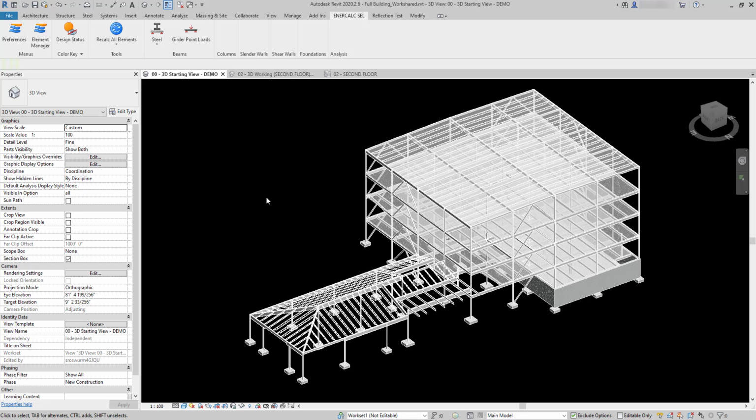In this video, we're going to be looking specifically at hosted Revit load objects and launching a beam that has those already existing in the Revit model. Now, as I mentioned in previous videos, it's perfectly acceptable to mix and match hosted and non-hosted loads. We're just looking at those in separate examples for clarity in the demonstration.